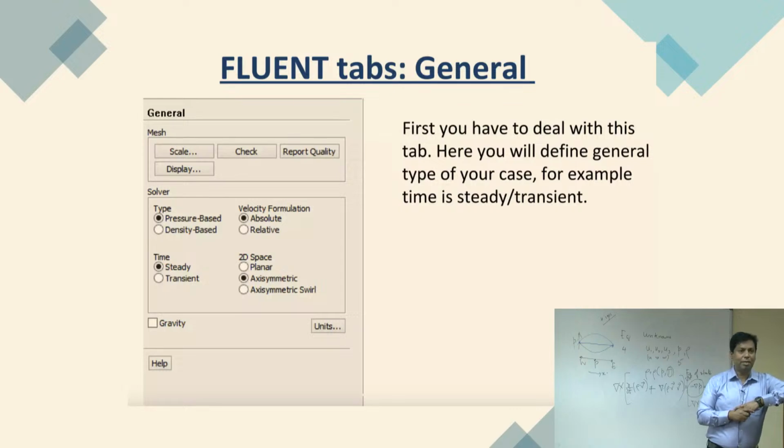In natural convection there is no external force. If you heat one surface, that heat can conduct through the wall and come inside and then hit the air, and the air starts to rise. That is called buoyancy, so we have to turn the gravity on. Even in our lung problem, we have to use gravity, because particle deposition is sometimes due to gravity. If it is heavier, it goes that way. But in some microfluidics cases, generally they do not use gravity, because gravity is neglected, the cases are very small and you do not need it.